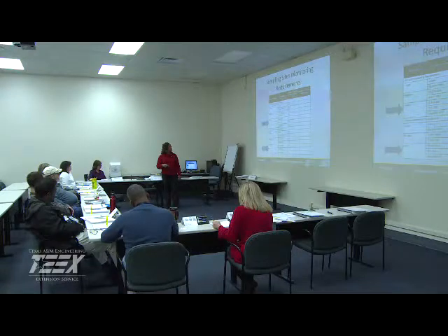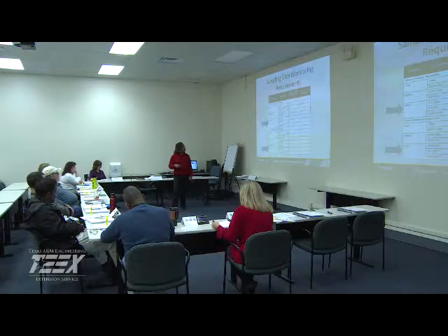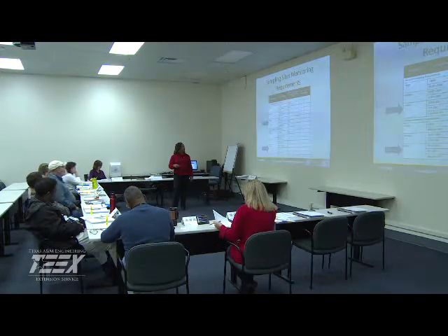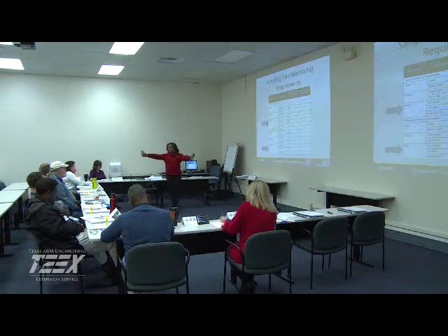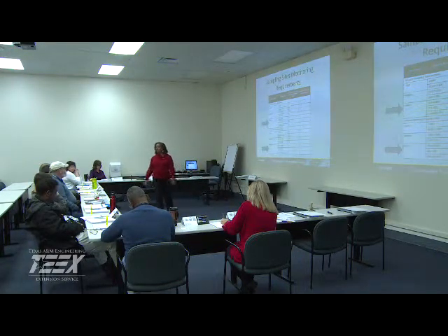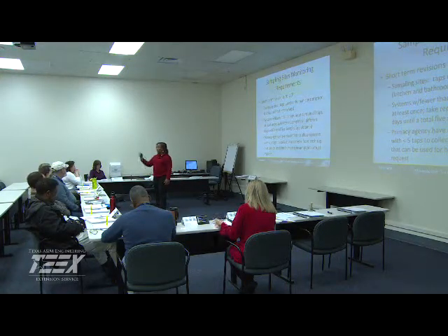With reduced monitoring, for less than 100 it stays the same, because the EPA says you have to have a minimum of 5 sampling sites. For 101 to 500, you can be reduced down to 5, and for 501 to 3,300, 10. And how do you qualify? You have to have your first rounds of samples all clean, 2 consecutive rounds.